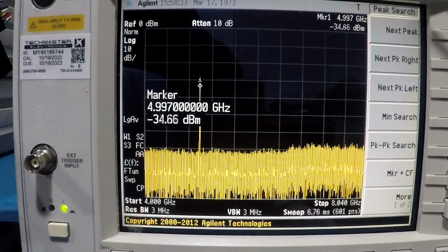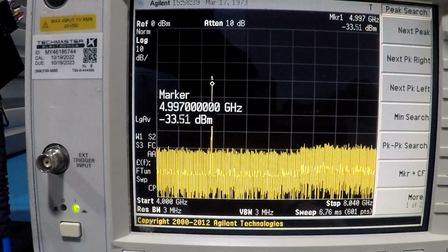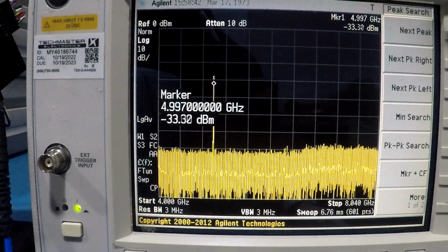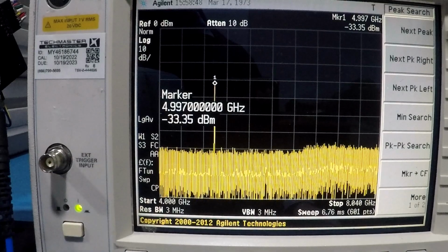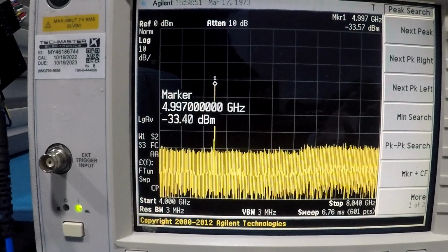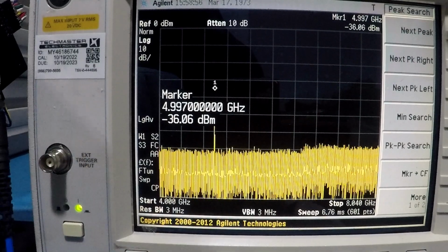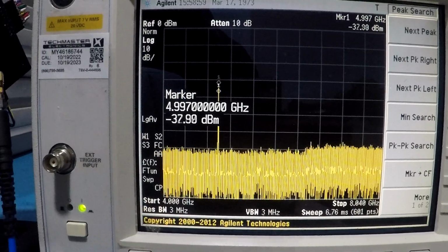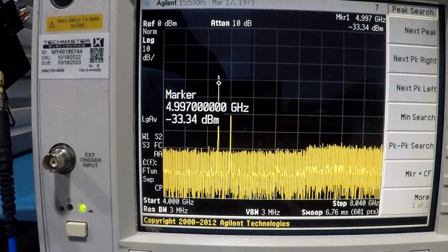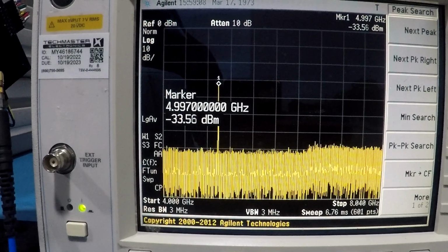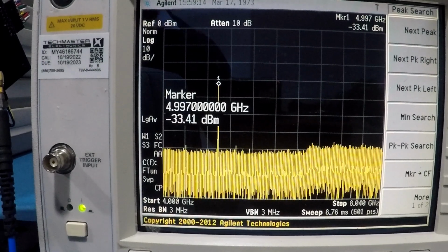I could get about 15, 20 or so dB of attenuation. We are in the near field, so we are going to be picking up some of the reflected signals off of the conductive base, the aluminum mounting plate that I have this on. So we won't completely block out the signal, but for the most part you can see that we can really drastically change the amount of received power. Okay, so now I'm going to get the top signal generator, the one we're going to use for jamming this signal, and we'll see what the AI does then.